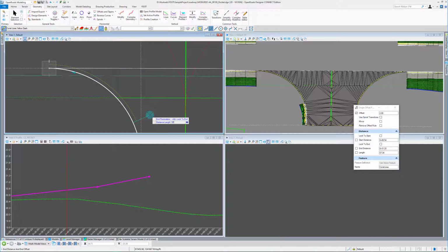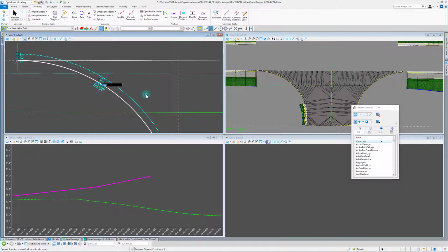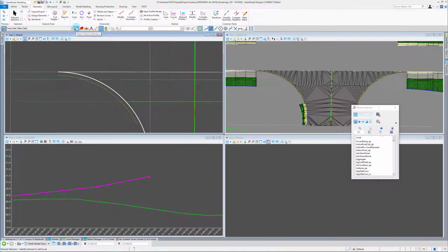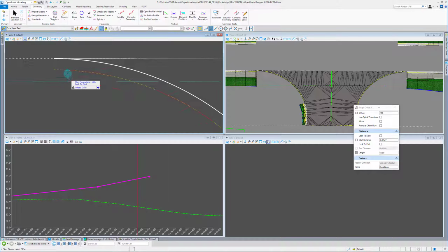So I'm going to go about, let's say, 55 feet. And it just drew on the wrong side, so we'll just flip this over. So I'm going to get now on my red line, and I need to do single offset partial along there as well. And what I've been doing with a lot of these curb ramps is I go 3 feet from the PT to kind of give us some space for the curb ramps so the curb ramps are not right up next to that PT.